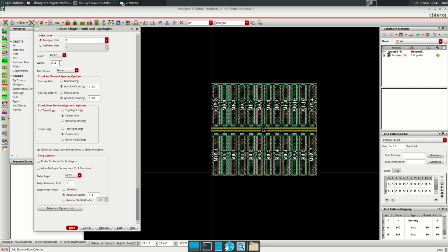So for this exercise, I'm going to use 1.5 micrometer, which will allow me to put a few contacts, because there is another issue also when we are doing analog layout: we should try to avoid very few contacts for reliability issues. We change the minimum spacings to 34, not to play with minimum spacings here, and then I think we are settled with that.